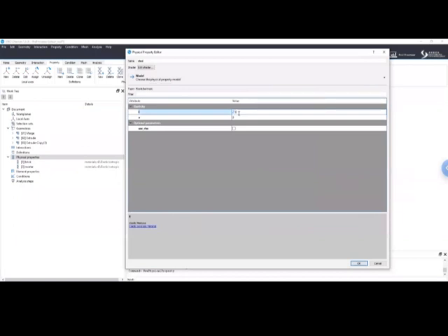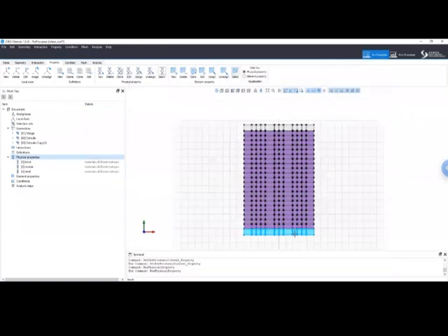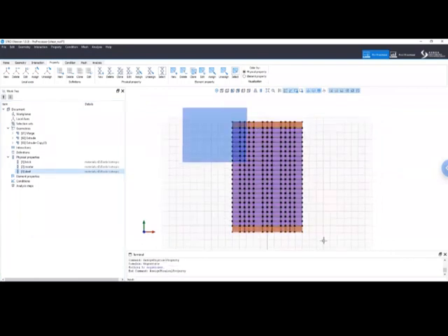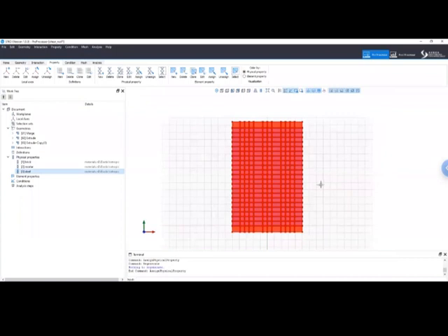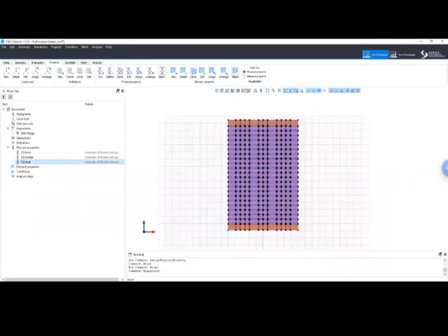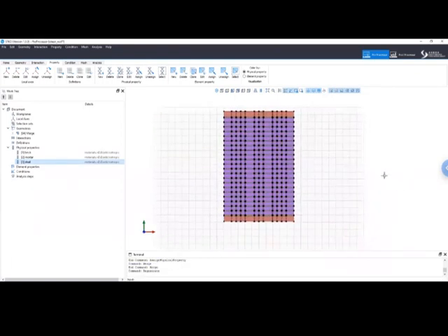By the way, I'm modeling in Newton and millimeters. So these are the units. 25, okay. I select this one, and I drag and drop the steel material model. Okay, now that we are fine, we finally join everything into a final merge. Okay. So now our geometric model is completely done.